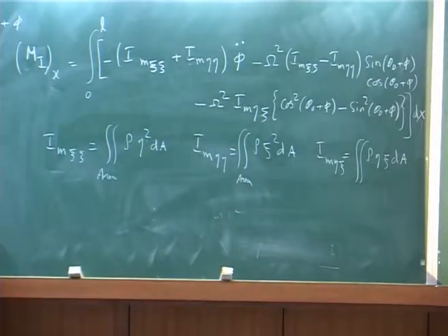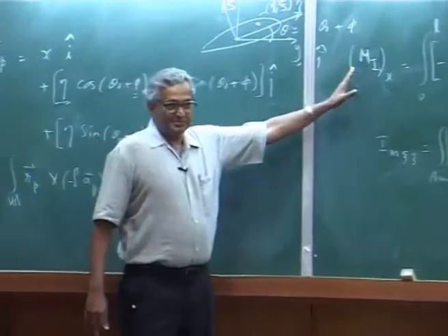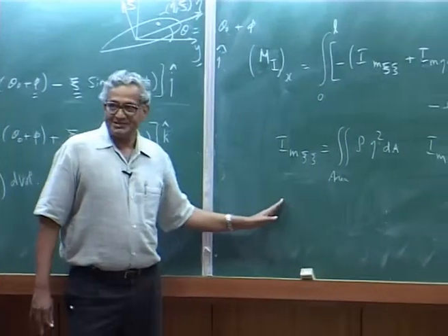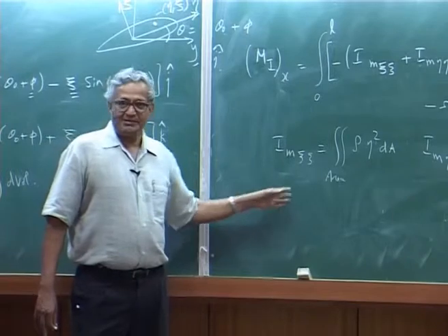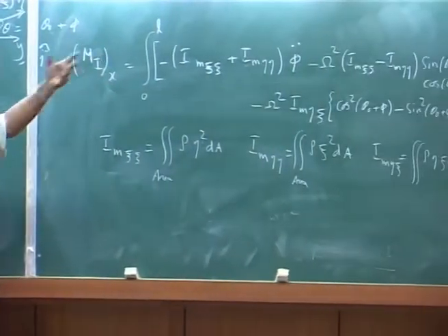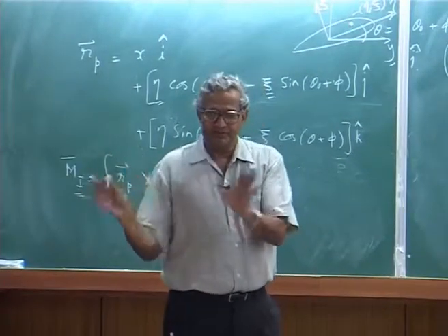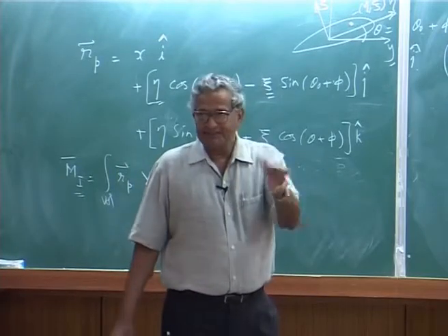Now this is my inertia moment, and I have to get the aerodynamic moment, and then the effect of the spring moment. When I add all of them, that is my equation of motion. So the inertia moment, I got this M_I, plus the aerodynamic moment, and then the spring moment due to the control system or all the combination, the torsional spring. You put all of them equal to 0, that is your torsional equation.